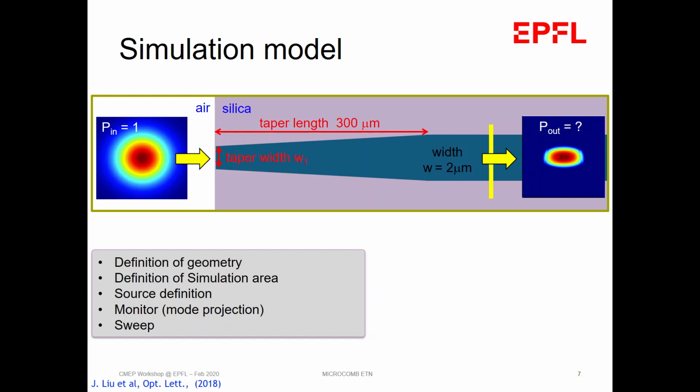We are not designing a fiber-based lens fiber here, because if you ask the manufacturer of these lens fibers, they will tell you that this mode has a mode field diameter of 3 micron or 2.5 micron. So we can just pick a Gaussian source from Lumerical that has a mode field diameter of 2.5 micron and use it as a source.